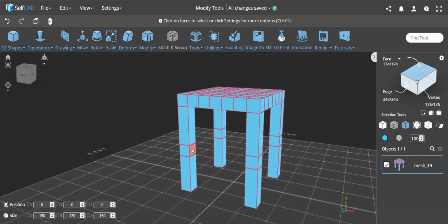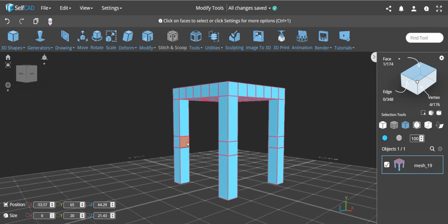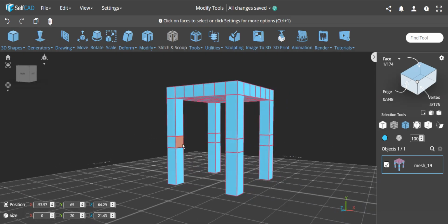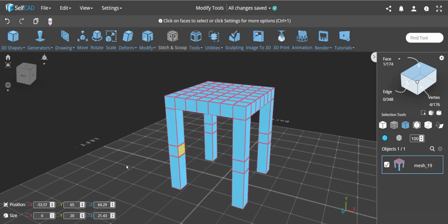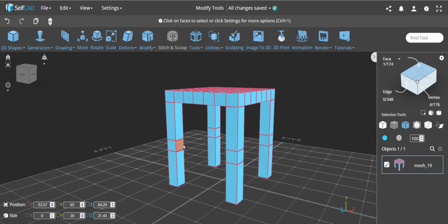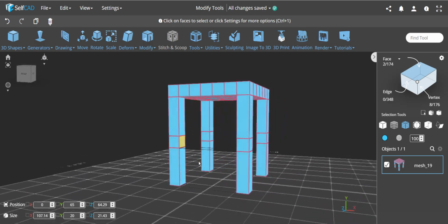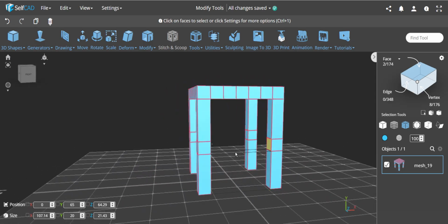Okay, so now let me show you why I'm talking about it, why this is important, because if we're going to extrude now this one, we know we always add, we move this face and we build only the side edges, but if I want this to connect to this one, actually I need to delete this face. This face needs to be completely removed. And not only this face needs to be removed, I can technically simply delete them and move the edges, but also this face needs to be deleted then. But not only the faces need to be deleted, they also need to be merged vertices.